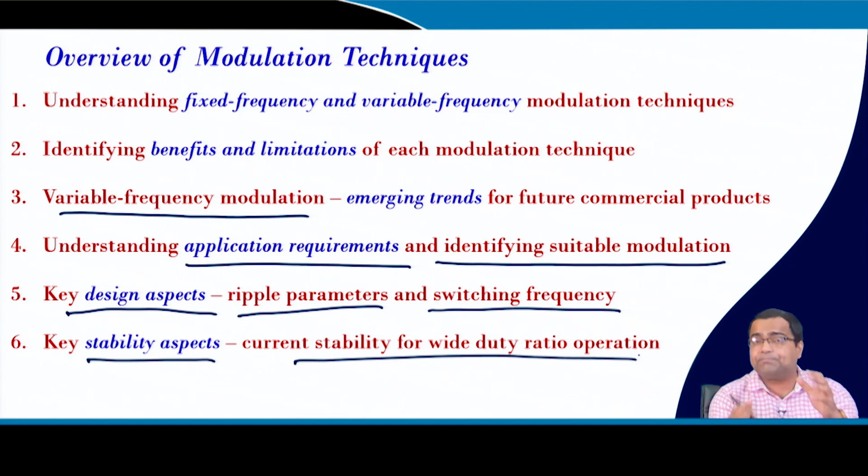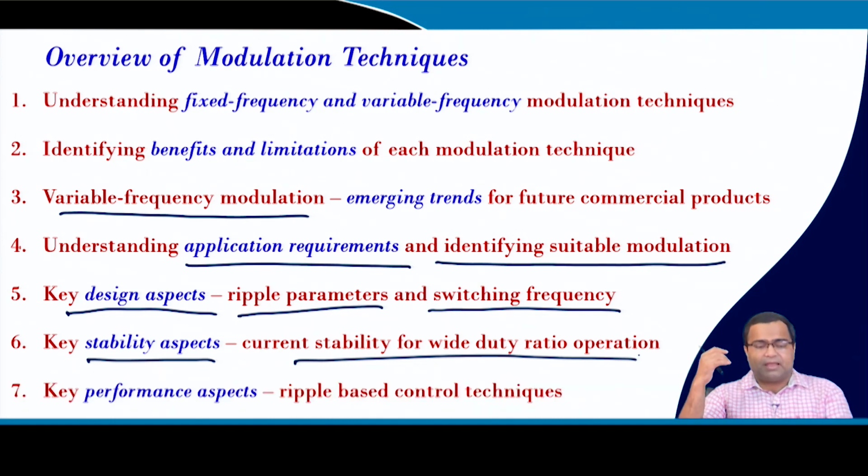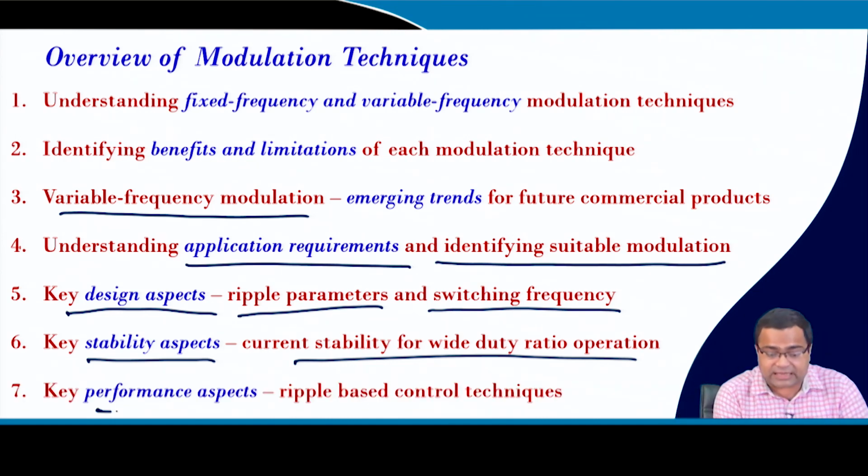And also in many precise applications where we need to track the average current precisely, and track the ripple parameter precisely, this ripple based control can be very useful, where we may not need to use any ramp compensation. Another aspect is the performance aspect.